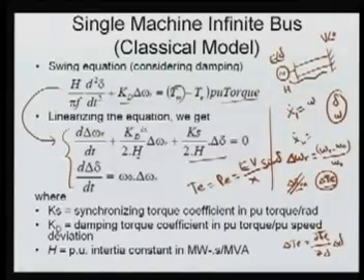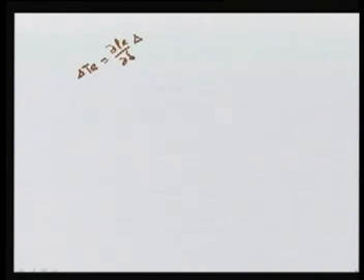So if you are differentiating this term with reference to your delta, I'll show you here. The change in your Te will be, I differentiate this P with reference to your delta, and then it is your delta. So what is happening, you get E V by X cos delta, times your delta.